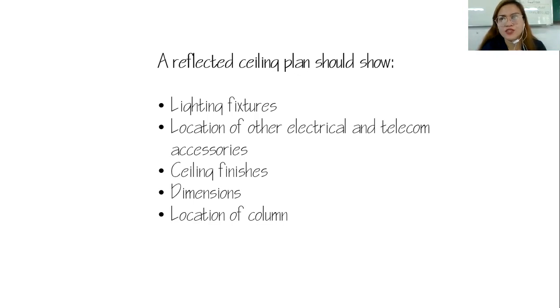What's the elevation from that area to the finished floor line? If that is 2.8 meters from the finished floor line, you need to indicate it through an elevation marker.